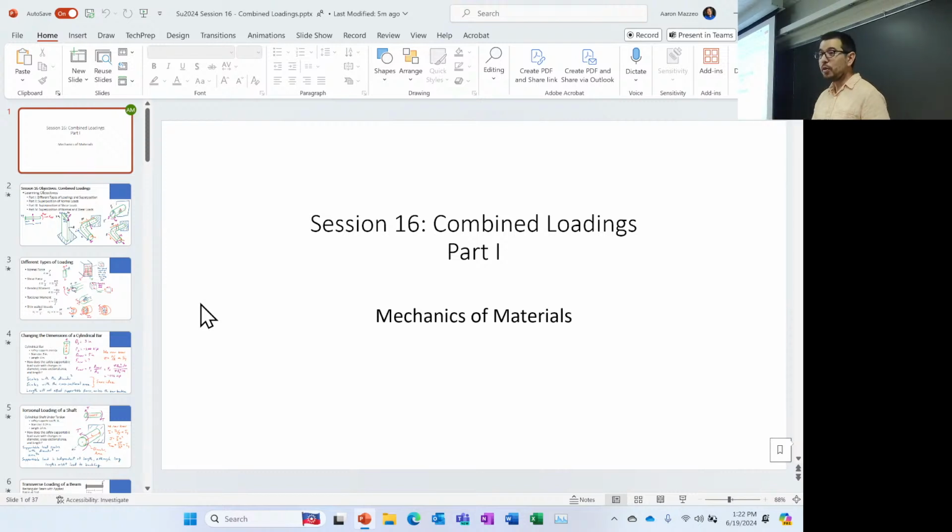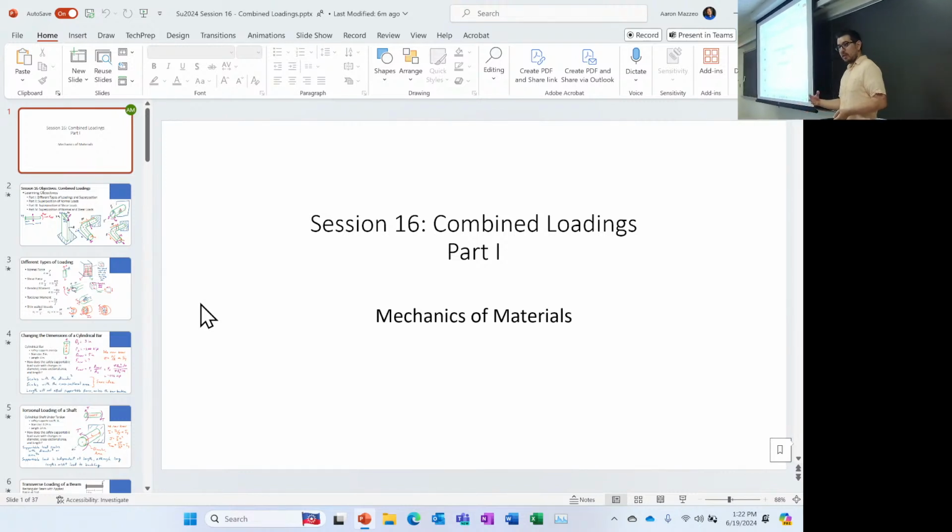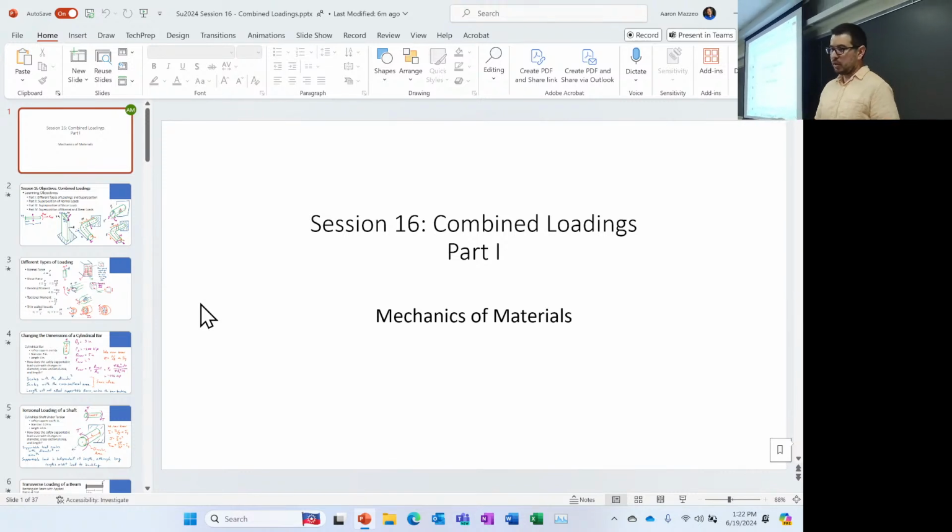It's also good for bumpers on cars. Okay, so you create these materials that can absorb energy, and then you avoid having some of the accidents that you would have. I'm not sure exactly which processes they use, but at least back in the 80s and 90s, a lot of bumpers were made with a polyurethane foam on the inside. They have a hard shell on the outside, but polyurethane on the inside. This material has all these bubbles in it and absorbs energy, and the way they make it is a process called reaction injection molding.